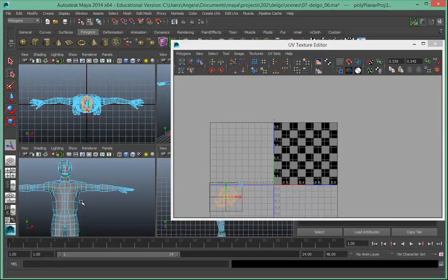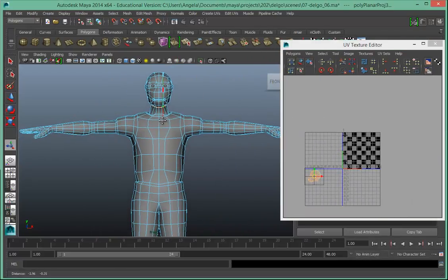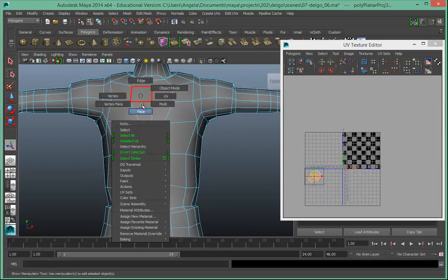For the interim, or for the brief time here, what I am going to do is reselect the faces on the chest plate area, so this character has the opportunity to wear a necktie, a bow tie, an opened jacket or a vest, a belt buckle, and whatever it is that I design in the front, it will not design it on the back as well, because I'm going to reproject it. So in doing so, I'm going to move this off to the side, get nice and close and personal with the front of our character, and now you've got to be in face mode to do this.